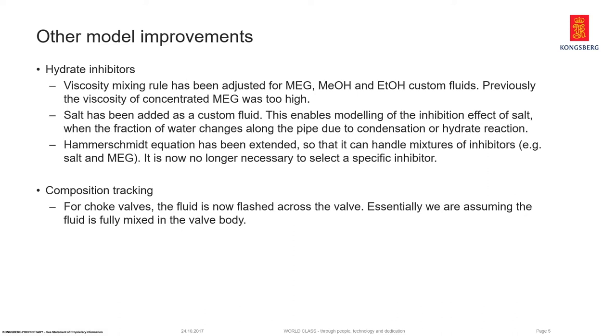Some other model improvements that are worth mentioning. So for the hydrate inhibitors and custom fluids, the viscosity mixing rule for MEG, methanol, and ethanol has been adjusted. So previously, particularly the mixture viscosity of concentrated MEG was too high. So this happened when the glycol fraction was above